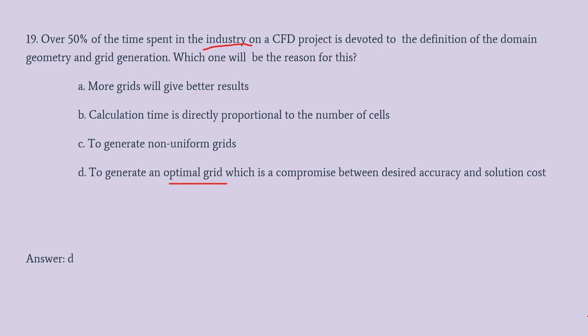Then, even we won't be going into that much, but we will look at the portion where it retards, like how the change happens. Suppose I have a mesh with 2 lakh nodes, and then I reduce the delta x and delta y values, so I get a 5 lakh mesh, then again a 10 lakh mesh. I will be comparing the results of the 2 lakh mesh with the 5 lakh, and the 5 lakh with the 10 lakh.